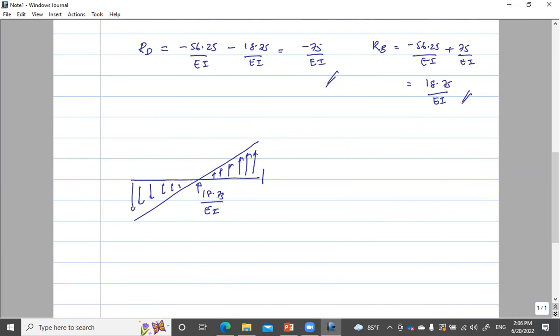Now this is shear force V and this is moment M. The reason I took this side is to keep my sign convention. Otherwise I had to go to the other side and my entire sign convention will flip. I have to keep on this side. Just imagine even a simple bending moment diagram, we need to be very careful. You can take the other side of the beam, but I took this side.